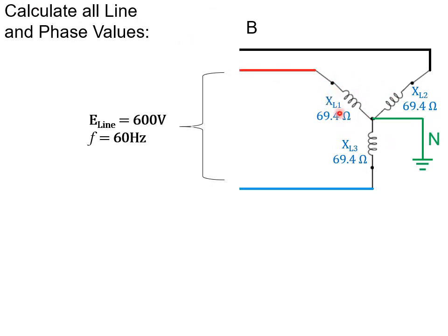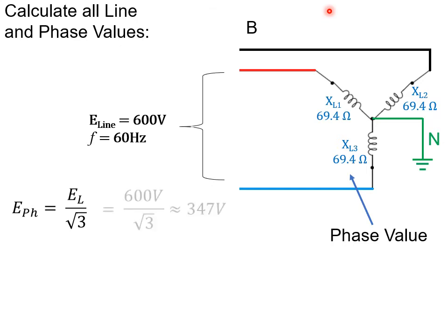Since our loads are inside the shape and they're a phase value, we are going to need a phase voltage. So that's the first thing you'll need to calculate. Our phase values are smaller than our line values by a factor of √3. 600 divided by √3, that'll actually give us 346.41 volts. But I have given the stated nominal value of 347, which is an acceptable answer.